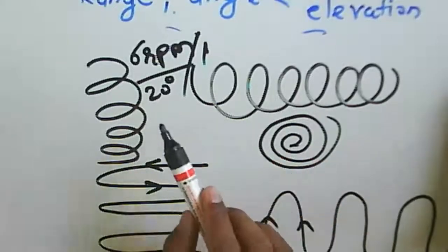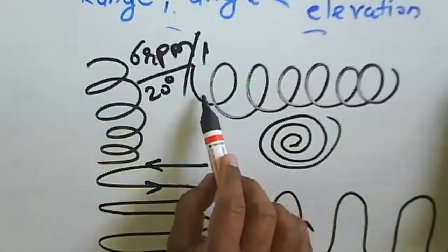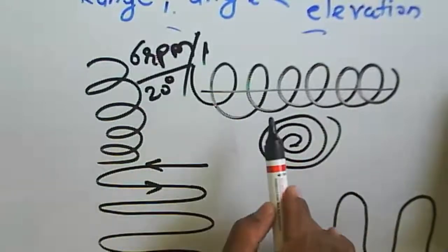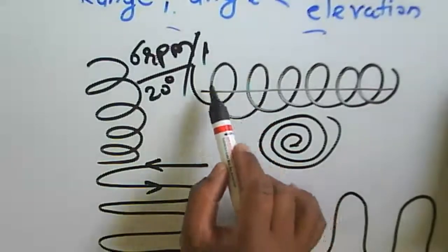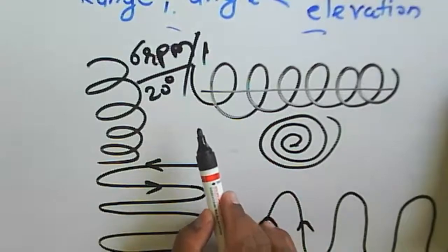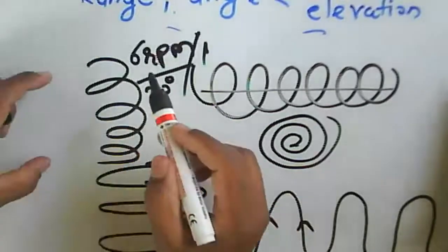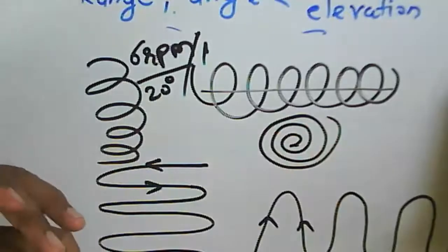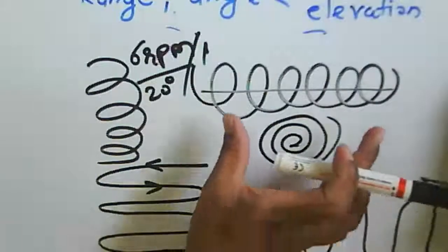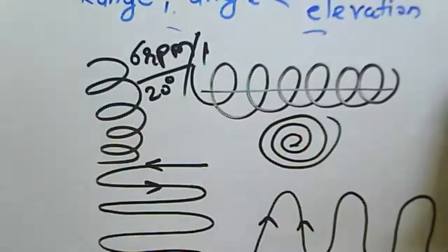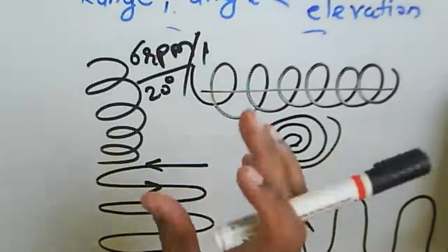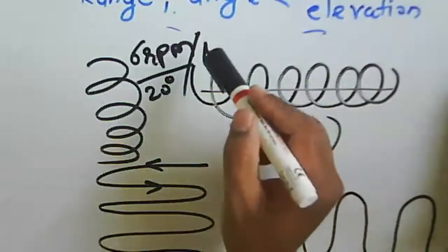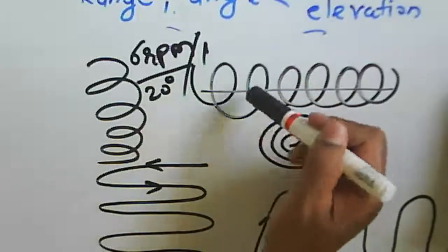So if you consider that this axis is stationary, in a Palmer scan the axis is stationary, but it has some linear movement, and this will be produced by the conical scan. In most of the cases this helical scan as well as this Palmer scan are used, because they are continuously tracking the target, and they are moving linearly. So if you consider conical scanning, sequential lobing, or monopulse tracking, in this case mostly the Palmer scan is used here.